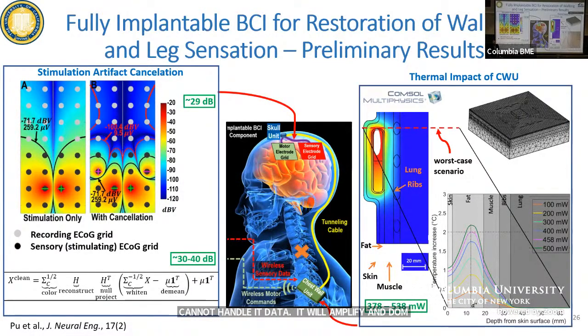We discovered that if you introduce another auxiliary dipole, given here in purple, with polarity exactly opposite to the primary dipole, and this auxiliary dipole can be as weak as 10% of the primary one, you can drive this contour downward. The black contour can be pushed, and you can clean up the signal. Let's say you really don't want the top saturated because this is where you're recording from the motor cortex. You can completely free up the motor grid by pushing these contours with a very small auxiliary dipole, so much so that you can get almost 30 dB of artifact suppression. Think of this as a spatially controlled signal.